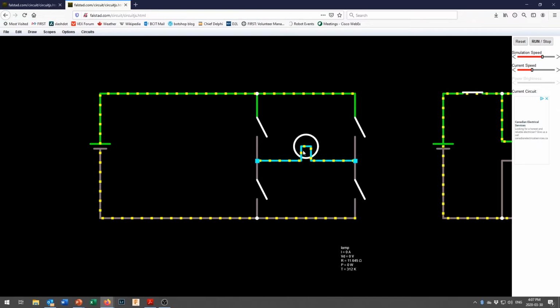One thing you do have to watch out for with manual H-bridges like this is that if you turn this switch on and this switch on, you're going to run into a problem and it'll all shut down because you'll have a short circuit right through there, and your circuit will just say, "I'm not doing anything more for you." So that's how we can control the motor's direction.